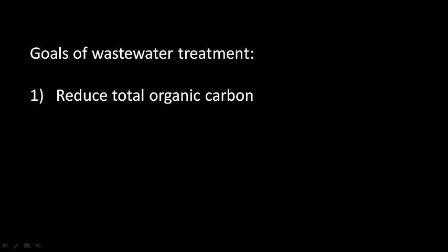So let's start reviewing now that we talked about the three different goals of wastewater treatment. The first goal is to reduce the amount of total organic carbon in the water. I talked about this thing called biochemical oxygen demand, BOD, okay? This is the concentration of oxygen that aerobic microorganisms need to decompose all of the organic matter that's in the water. So it's essentially a confusing way of measuring the amount of total organic carbon in the water, but it's measured via the amount of oxygen that would be needed to decompose that organic matter.